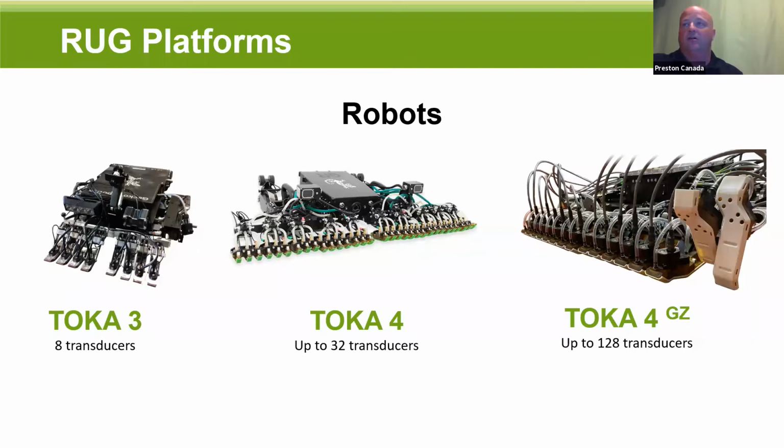Well, there are defects listed on that list that an ultrasonic platform is way more effective than MFL. There are some defects on that list, like small pitting that maybe fall in between that grid, that maybe MFL is a little bit better of an option for. So there really isn't a better way to do it. There is a way that's been done for the last 30 years plus, and that's been MFL. But MFL does not get you accurate data points down to the thousandth of an inch like a UT scan.